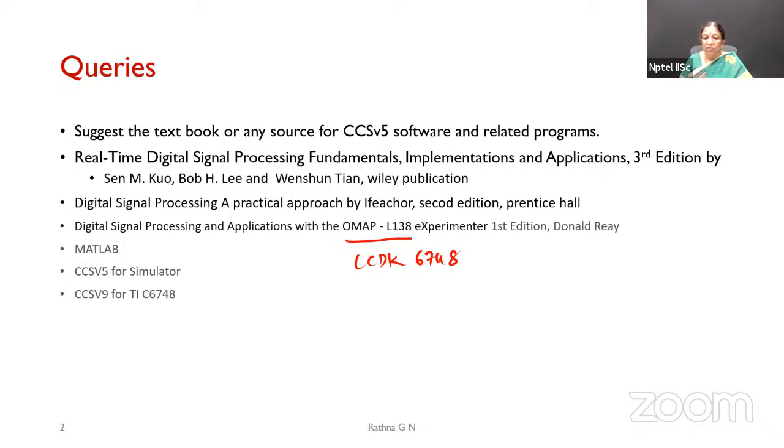And if you want hands-on experience with the TI 6748, I have used Code Composer Studio version 9. One thing you have to keep in mind is that these boards, even the 6713, work with compiler version 7.4.4. If you have a higher version, please load compiler version 7.4.4, make it the default, and then use it.